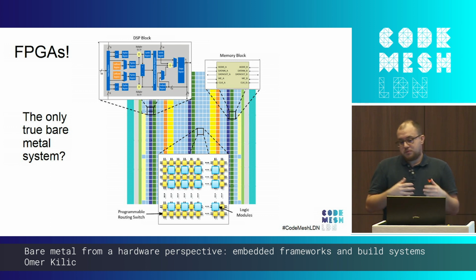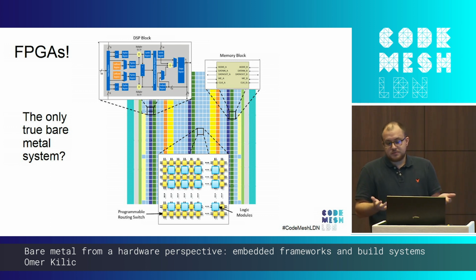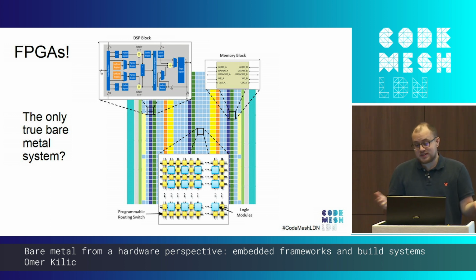So the logic description that you write, either in Verilog or VHDL, or these days there are much higher level frameworks that allow you to have quite nice representations of systems, like Python, for instance, compiled down to FPGAs. You can effectively build your own computer system, computer architecture. You can stuff 20 CPU cores in them if you want. And these devices usually have very advanced peripherals, very high-speed links, and generally a lot of very fun resources you can do a lot of stuff with.